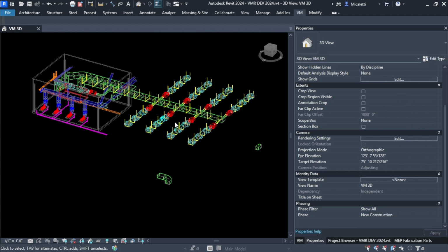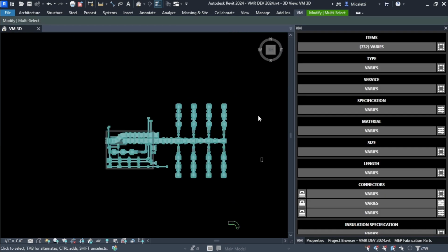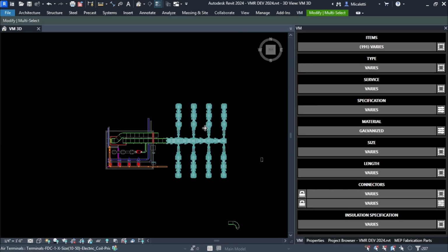So for the points, you're creating a schedule and then exporting that to a CSV to be able to get it to the total stations. Exactly. And the beauty in that is you're not scheduling the points, you're scheduling the items themselves. So the guys in the field, they can know everything about that pipe, like literally everything. What's the insulation? What size is it? What level is it on? What's the service abbreviation? All the power of Revit schedules are now with you in your point export.